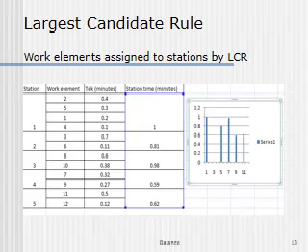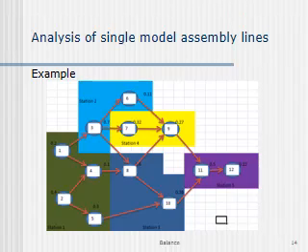Based on the station time, each station is executed. Each station is mentioned in one color, and based on the cycle time the precedence diagram is drawn in different colors for different stations, so the 12 operations are covered in 5 stations.